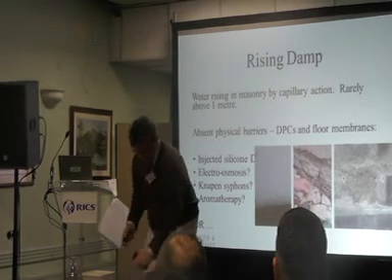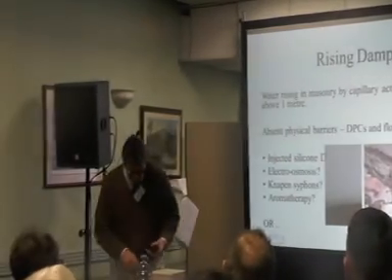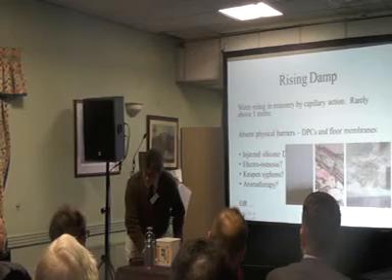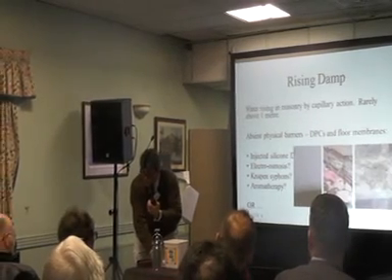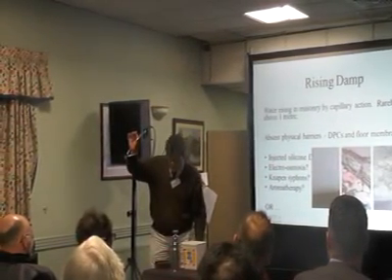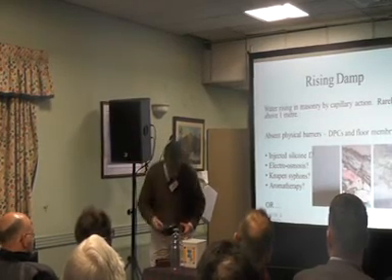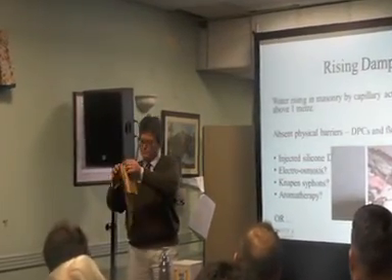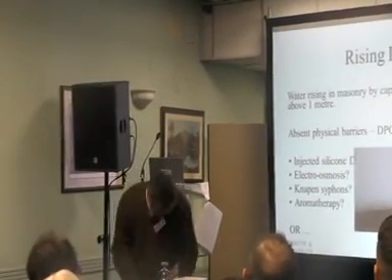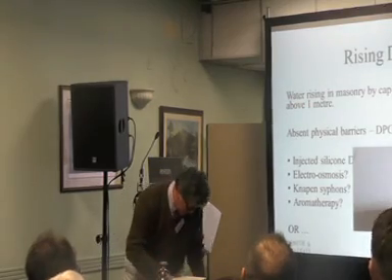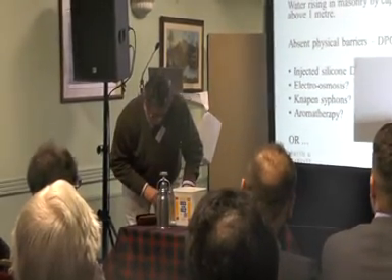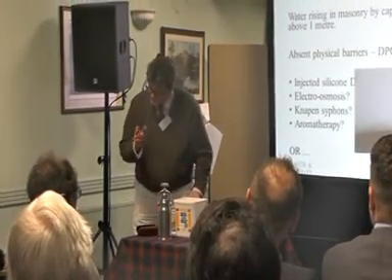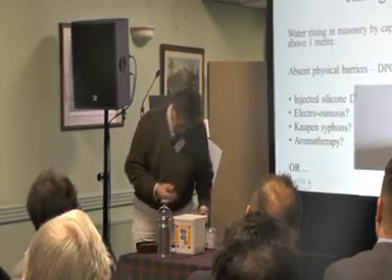So I'll just shout. The first thing is, of course, what it's doing is measuring conductivity. It's not measuring damp at all. It's just measuring conductivity. So I've got a piece of very conductive material. Now that might be a foil-back plasterboard, might be hidden behind a piece of soggy wallpaper, like Paul Daniels. Oh! So my meter may or may not, it's not going to, but it does sometimes, pick up the piece of foil behind the soggy wallpaper.